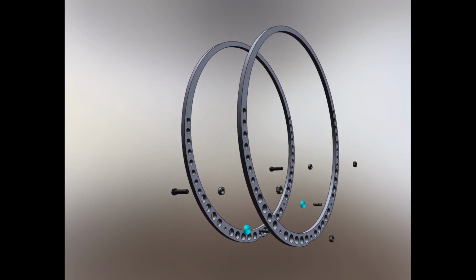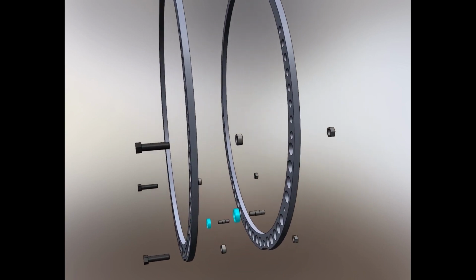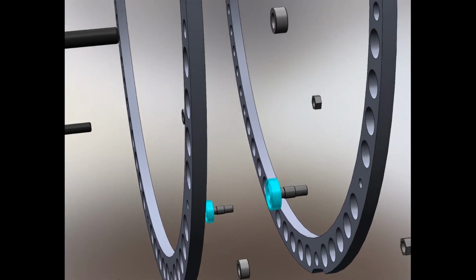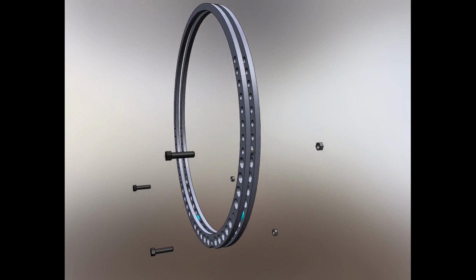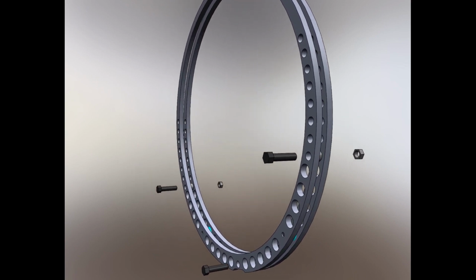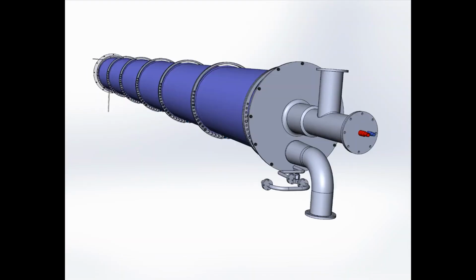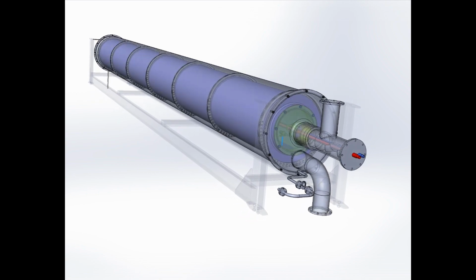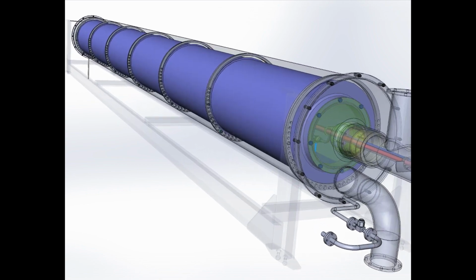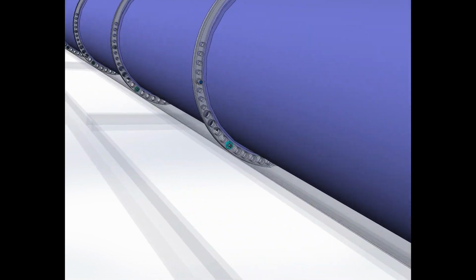To increase the space for installing ceramic bearings, the holes for the drum in the support rings are shifted upward by 25 mm. Uniform placement of ring supports along the length of the drum distributes the load, so ceramic bearings operate at loads much lower than designed, which has a beneficial effect on their service life.